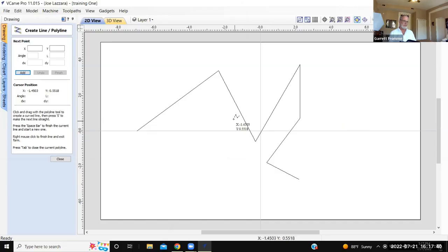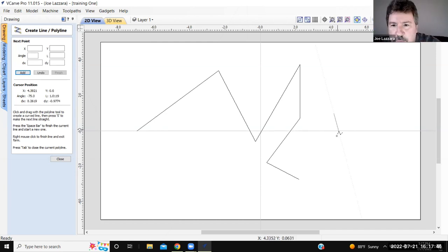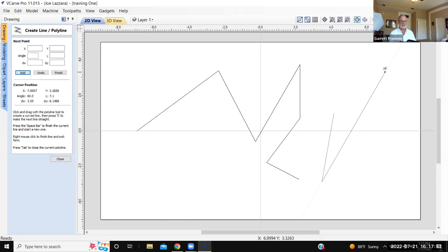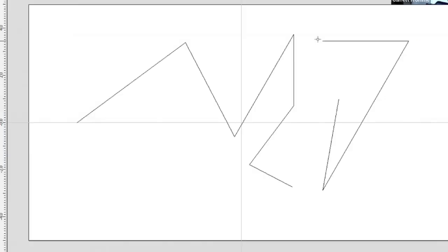So click the mouse again. Just click right there. And move. And do it a few times. See how you started new lines? Now hit your space bar again. Now go to that bottom endpoint. Either one, it doesn't matter. And look, your cursor turned into a square target. That means it grabbed the endpoint of that line. Now just click it and move. So you're starting a new line right there, and it grabbed it right at that endpoint.